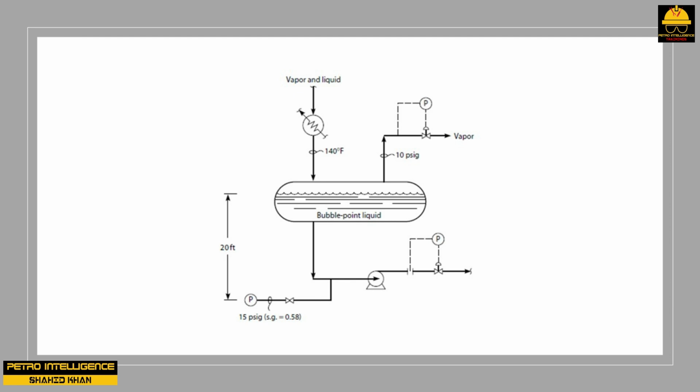This means that the required NPSH of a pump increases as the volumetric flow through the pump increases. The units of NPSH are feet of liquid head. The required NPSH of a pump is due primarily to the conversion of feet of head to velocity in the eye of the impeller. The available NPSH to a pump has the following definition.